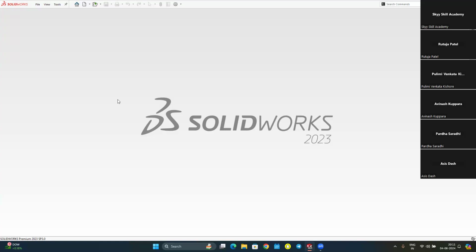Okay. So basically, the minimum thickness of sheet metal will be 0.6 mm as per Indian standards, and as per Australian standards, the minimum thickness of sheet metal will be 0.5 mm. And 0.5 mm or 0.6 mm to 6 mm thickness is called sheet metal. Above 6 mm is called a normal metal body. And below 0.5 mm down to 0.1 mm, it is called metal foil.